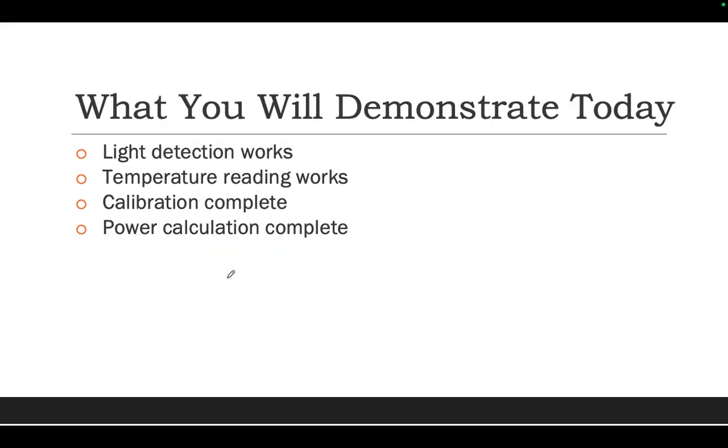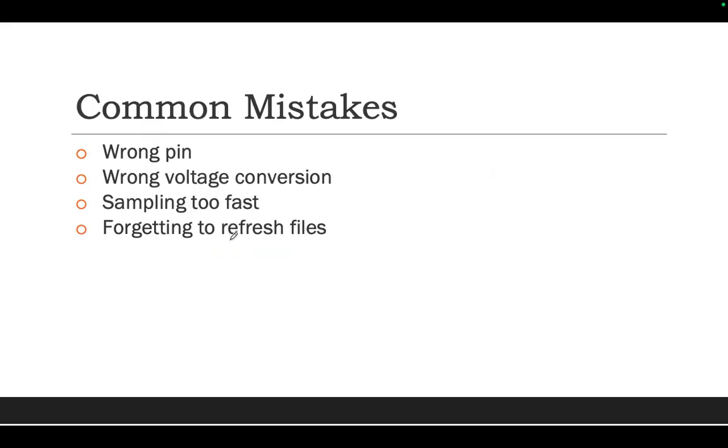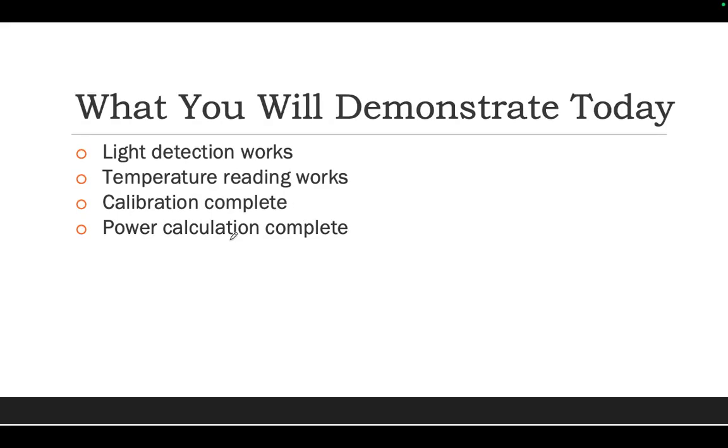Okay, what you will demonstrate today: light detection works, temperature reading works, calibration complete, power calculation complete. And this is what you will demonstrate. Common mistakes: wrong pin, wrong voltage conversion, sampling too fast, forgetting to refresh files. You need to pay attention to not make those mistakes.